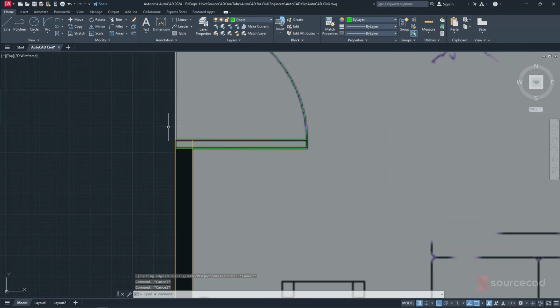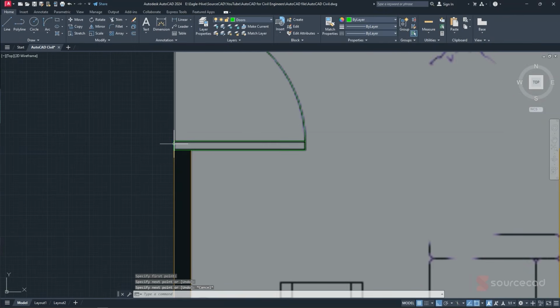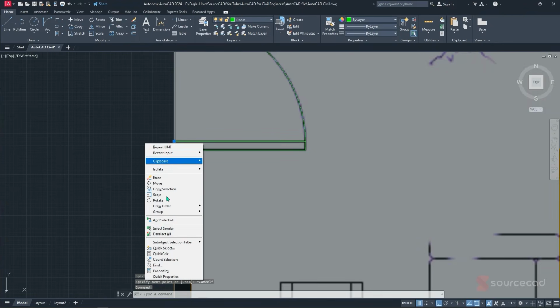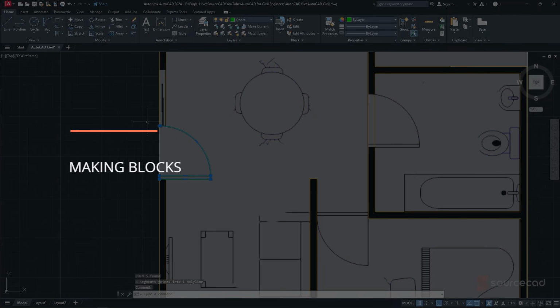For the door here, we can also just trim it so that we have our door looking like this. Now I'm going to just simply connect from this point to this point. Then what are we going to do? Simply select one of them, select similar, and select this one, this one, this one, hit on J. So the ones that can join will join. And after that, we'll just create it to a simple block.